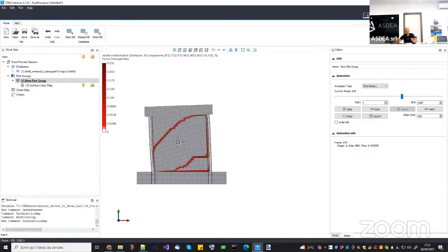Yeah, partially, because for example, in reinforced concrete, the microstructure is given by the reinforcement, but also by the aggregate size. So basically, if you have a finite element which is of the order of millimeters, it is smaller than the aggregate size in the reinforced concrete. So yes, if you place the rebars physically, you improve something, but you're not going to solve everything. Many times you don't need to do such a refinement because you want to use performant meshes, so you may want a coarser mesh.